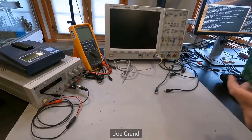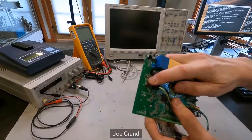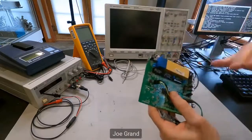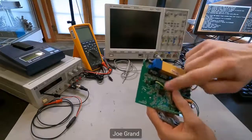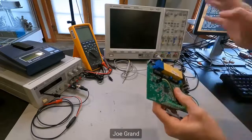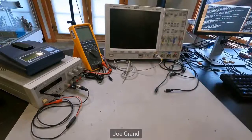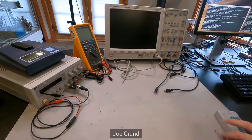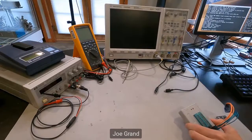Oh, I didn't mention, actually I kind of did mention, a lot of these systems are using these external SPI flash devices. So a very simple serial communication interface, and the firmware a lot of times is stored on a device like this and then gets read into the CPU on power up. These memory devices have no encryption capability, no authentication, no nothing. They're what I call dumb memory devices. So we can, with the correct tools, extract the memory contents from that device without having to use that bootloader and type stuff over and over again. We can just use a tool like a device programmer.